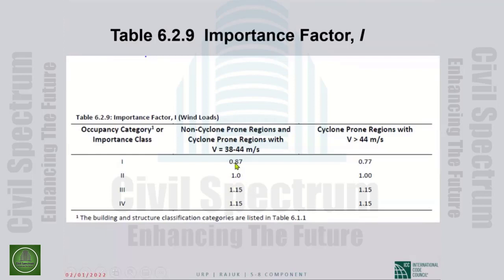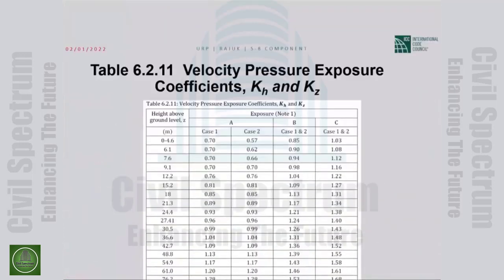To go down to 25-year return period, if you are in the interior, it is 0.87. If you are in the cyclone-prone region, it is 0.77. And there are reasons for the difference that, if there are questions, I will get into. Otherwise, I will leave it there.